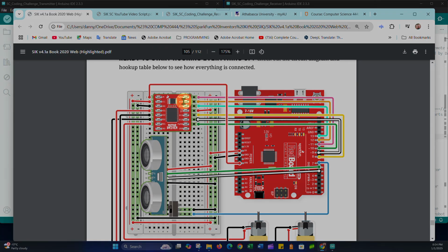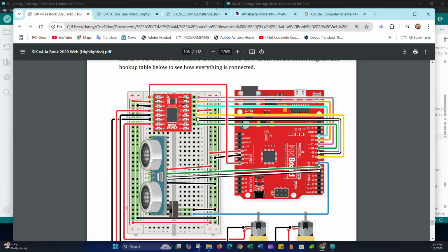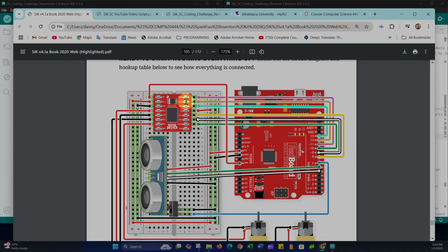For motor 1, channel A, we have our PWM pin A and our 2 input pins. They're hooked in here, and the channel B pins, so the second motor, are connected here. On each, the inputs A1 and A2 are your directional pins for motor 1. Similarly, B1 and B2 are your directional pins, and each motor has a PWM pin, which do have to be hooked up to PWM pins, pulse width modulation pins.